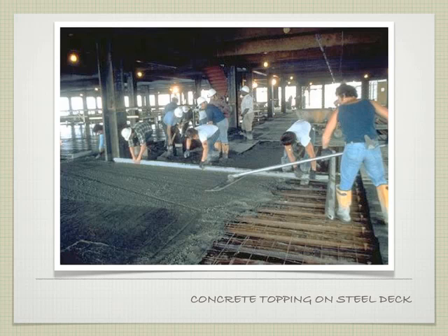They've got a screed board, so they fill in the concrete. They're using the screed board to get it level. After that, do you guys remember what they do? They float it with a bull float, and they actually float it again after they floated it once, followed by a trowel. Then depending on what type of building floor you're going to ultimately put on, you might put a brush pattern on it so it has a little bit of texture to bond whatever you're trying to do as your ultimate floor. You might want it perfectly smooth. It's going to vary depending on the finish of the building. But this is an example. Obviously, this is a little bit more complicated than a slab on grade, but it's the same concept.